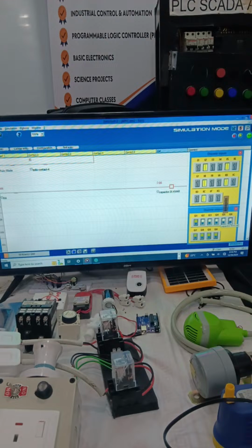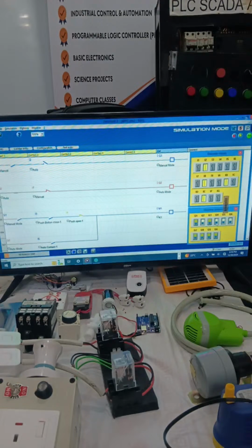Now suppose some inductive loads are switched off, like a blower, pump, lift or escalator. Then for power factor improvement, you need to reduce your capacitors, one switch off. So here the switch off is controlled by the controller, and this contact will open. Now still some further loads are stopped, so we need to switch off a 50 kVA capacitor.